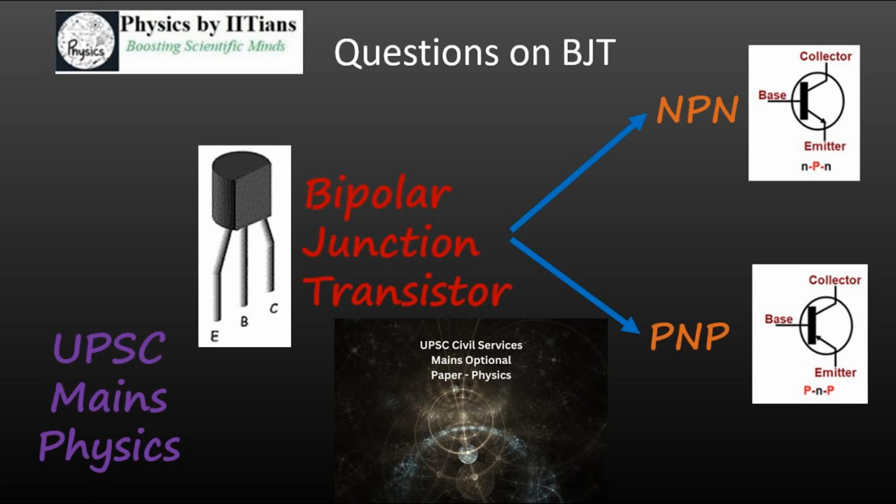Doping. N-type materials are created by adding specific types of dopant atoms to intrinsic, undoped, semiconductor material. Common dopant atoms used for N-type doping include elements from group V of the periodic table, such as phosphorus P, arsenic As, or antimony Sb. These elements have more electrons in their outermost energy level than the intrinsic semiconductor material, usually silicon or germanium. When they are introduced into the crystal lattice of the semiconductor material, they create additional free electrons.